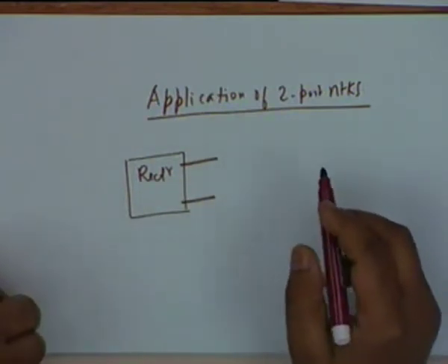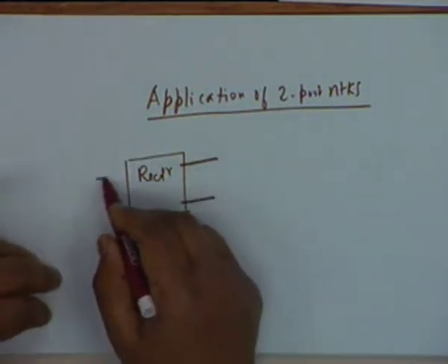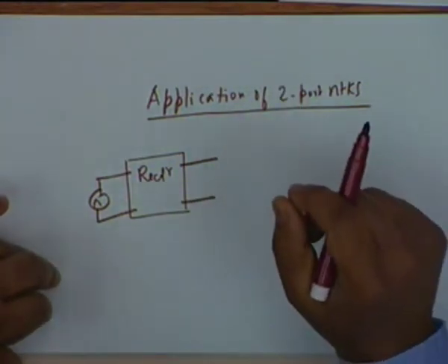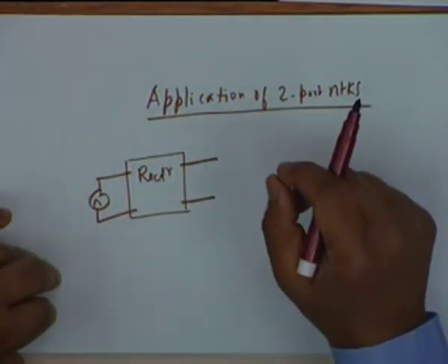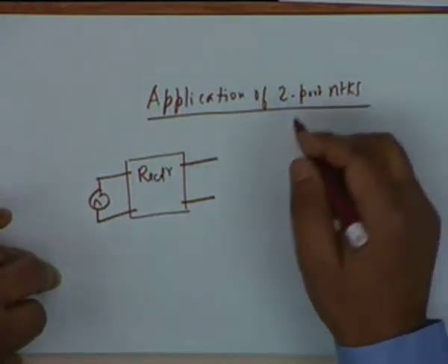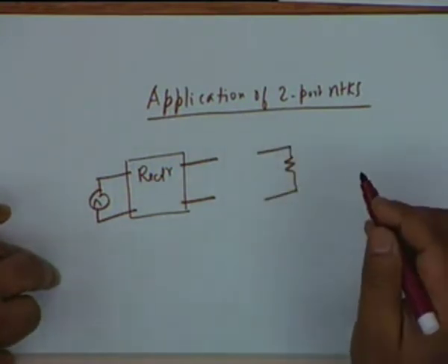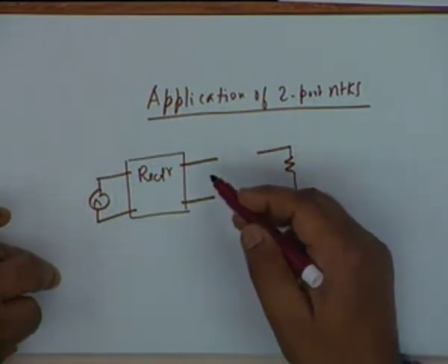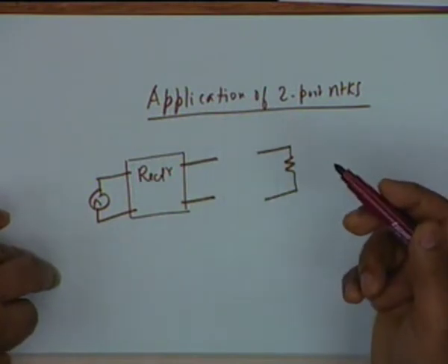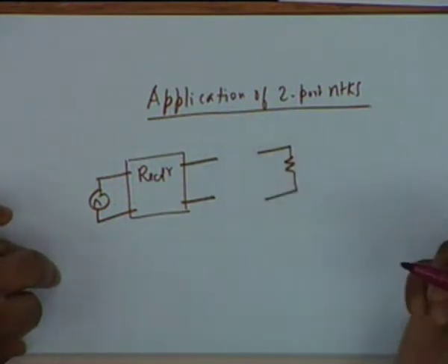You have to supply. What does a rectifier do? Rectifier is also a two port. Isn't that right? It takes an AC at the input and should produce a DC. It doesn't. It produces a DC on which is superimposed a ripple or an AC. You wish to drive a load with this DC, and if you want to improve the DC content or reduce the AC content or reduce the ripple content of the output, what do you do? You apply a filter in between.